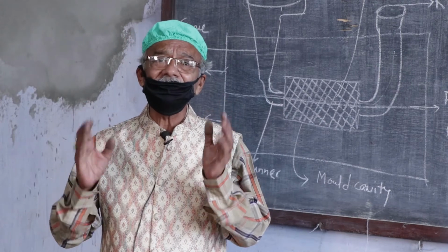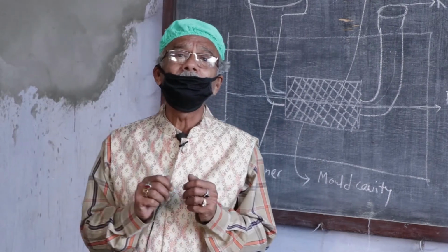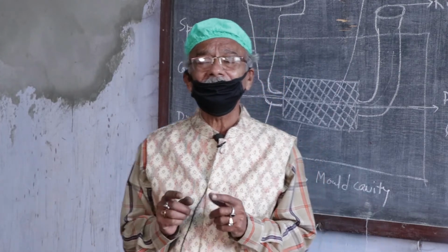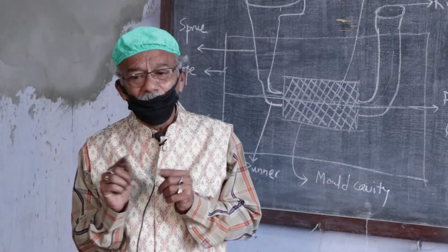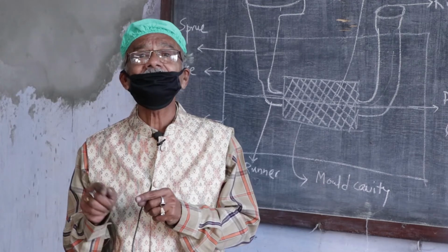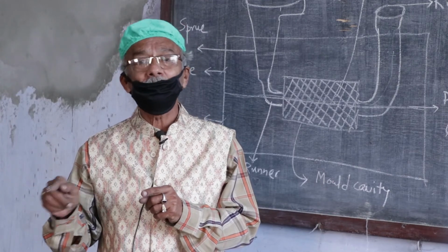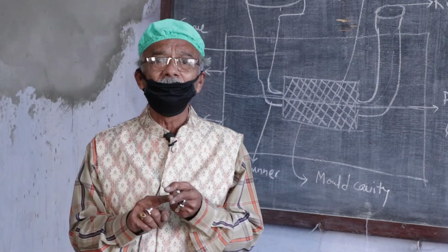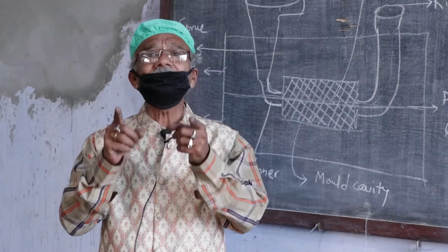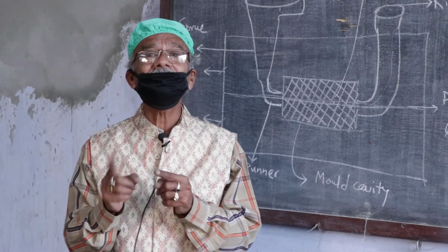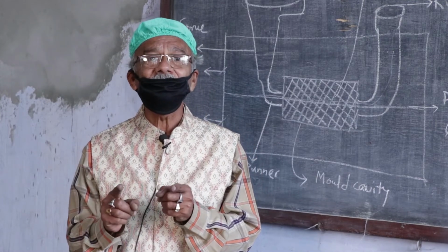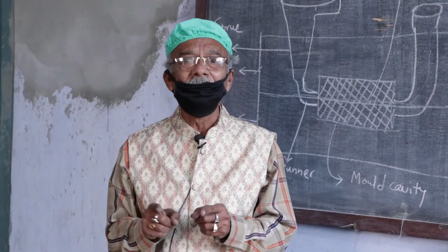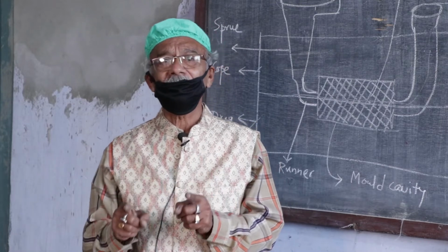If the casting size is large, it is not possible to break it and check it. So, there are different techniques known as NDT tests. The full form of NDT is non-destructive testing. But whatever the process may be, machining, casting, or forging, human eyes play an important role. That is the best master to find out defects, either in machining, forging, casting, or fitting, whatever it may be. So, go for visual inspection at first.